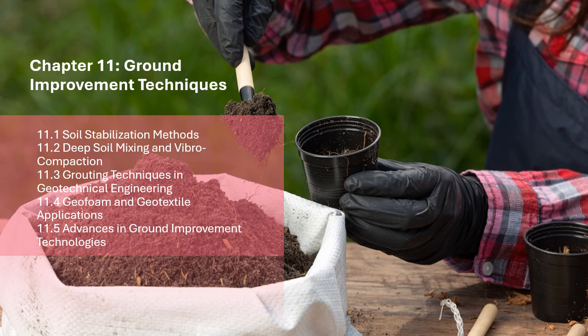2. Soil compaction. As the vibroflot vibrates, the soil particles are rearranged and compacted. The process effectively reduces the void ratio between the particles and increases the density of the soil. 3. Soil improvement.